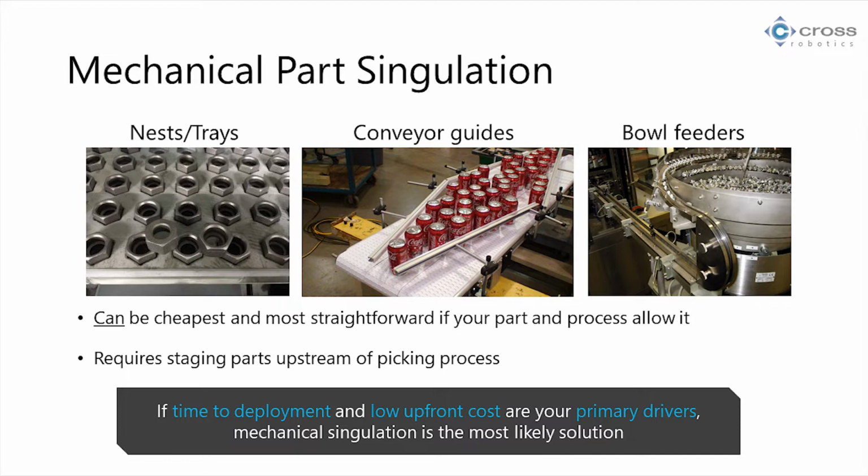This requires that you go upstream from your robot process and figure out how to actually stage your parts, right? So the slight trade-off there, it's super simple, but you need to handle the part and do some work to make the parts consistently presented to the robot.